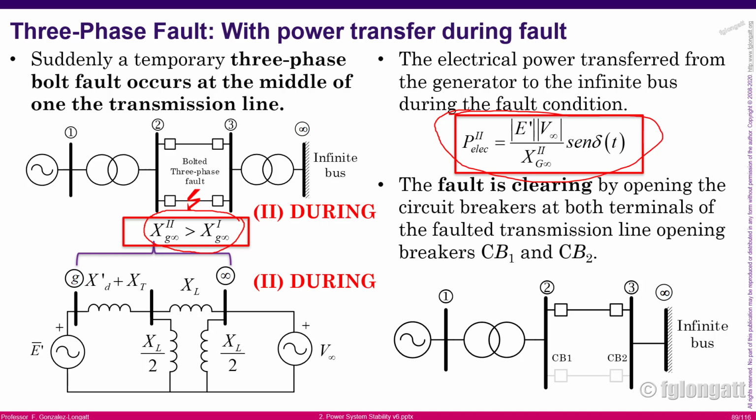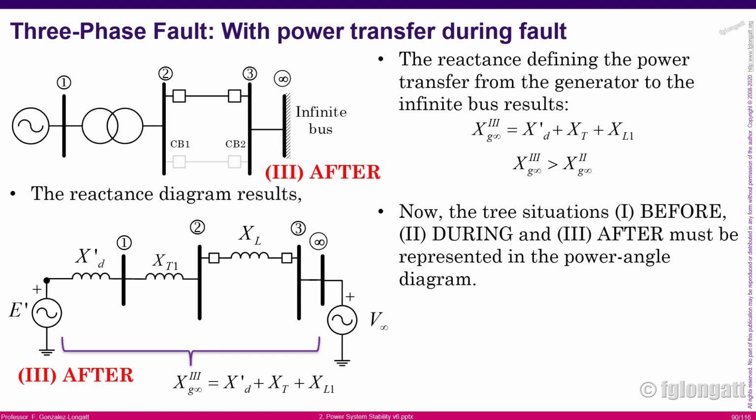I will not discuss this because I don't have a numerical example to show you here, but you must understand that. Then this is a more realistic example, because in real life, faults tend to happen on the transmission lines. If we have a fault on the transmission line, of course the overcurrent protections and the distance protections connected to the circuit breakers will see the fault. As a consequence, they will open the circuit breakers associated with that line. Right now, we have this transmission line out of service. As a consequence, the power system will keep working in emergency conditions because it was a contingency.